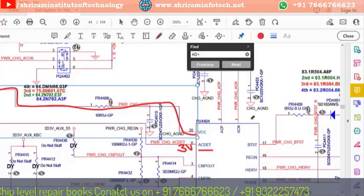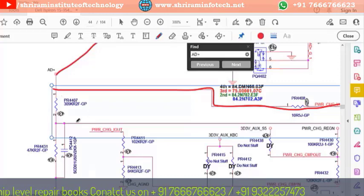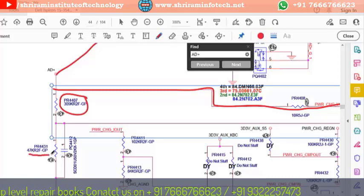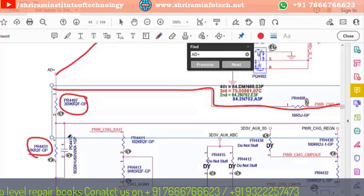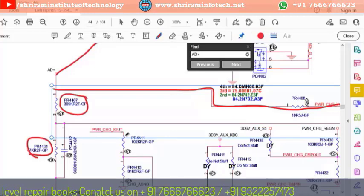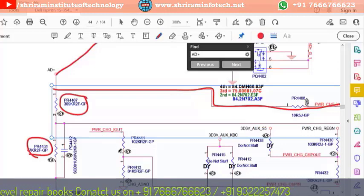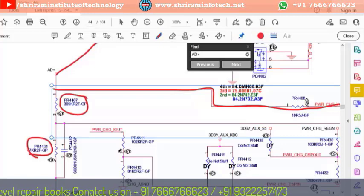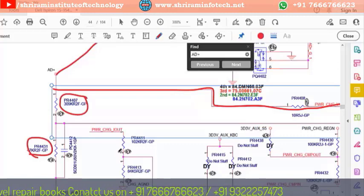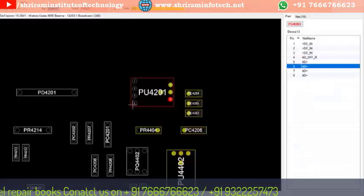Okay, so how will this 3 volt come here? By a divider circuit, these two resistors PR4407 and PR4431. Suppose the 3 volt does not come here, and it is 0 volt even though you have connected the adapter. How will you find the location of the resistor? The same thing: go to the board viewer and type the location PR4407 like this.